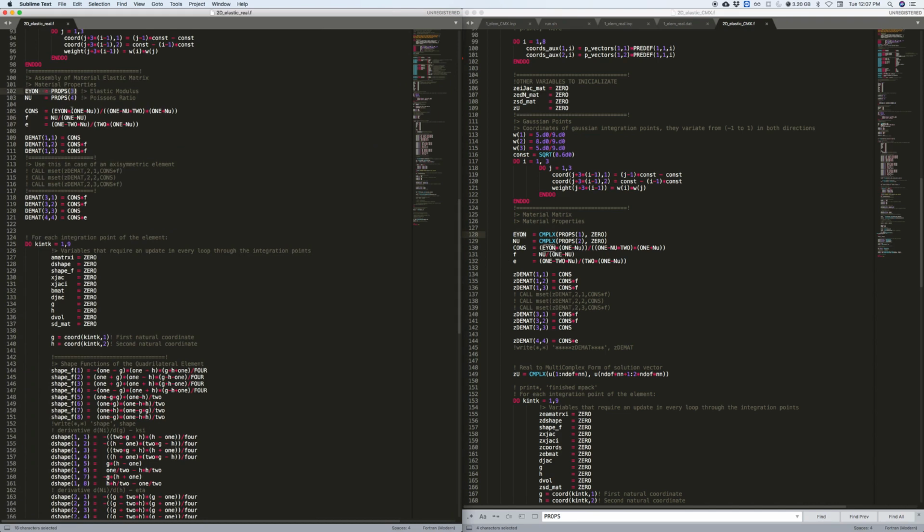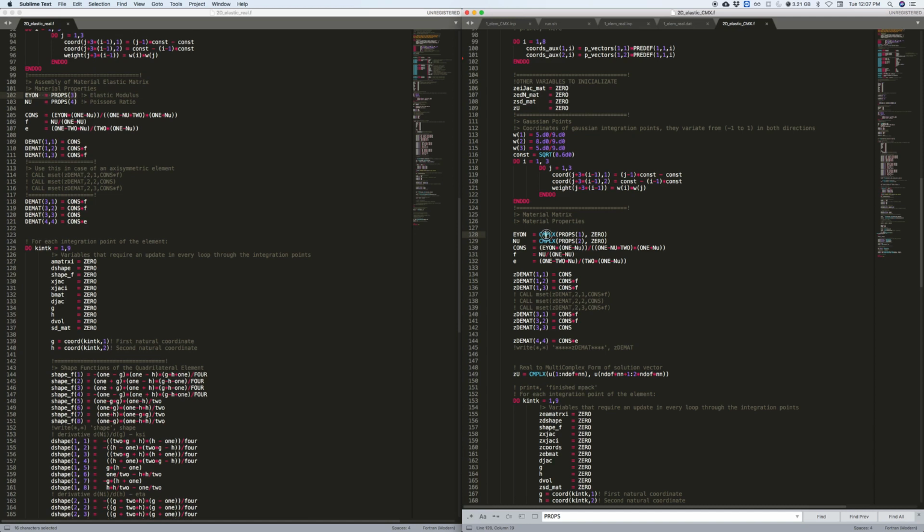You remember that it was the property number 3. In here it is a complex variable, right? And the real part is the property number 1, which is the normal elastic modulus. And here the imaginary part is going to be 0, right? Because I'm not perturbing that input variable. If I want to perturb it, here I just apply a perturbation, let's say 1 to the negative 10. Okay, but right now we are not going to apply any kind of perturbations.